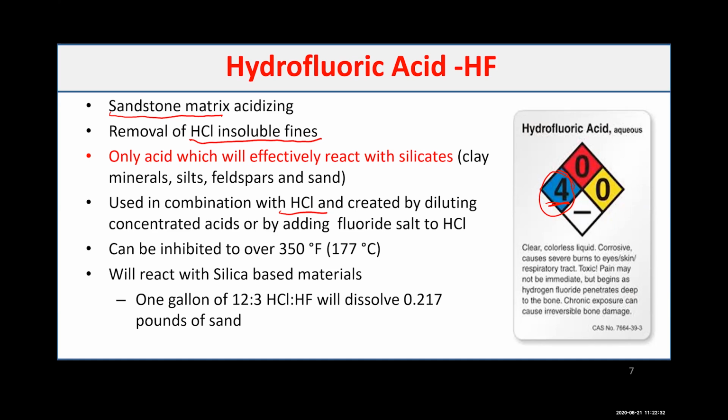We can use HF up to 350. We can inhibit it. We have no problem. We bump the job again at really high temperature, which is a good benefit of having this one. And again, we mainly use it to dissolve the silica or sandstone.